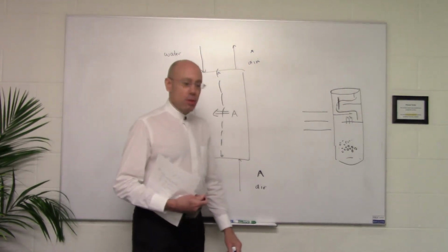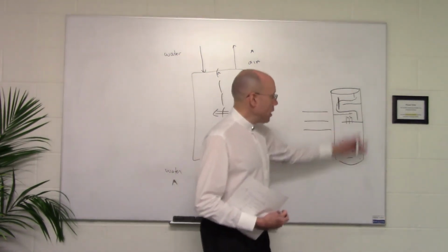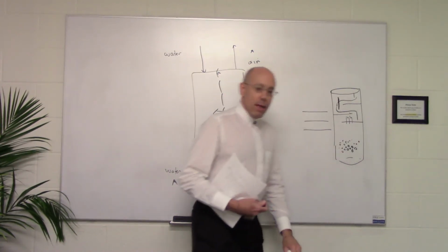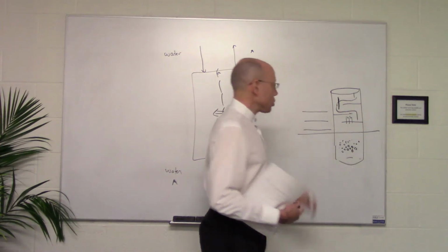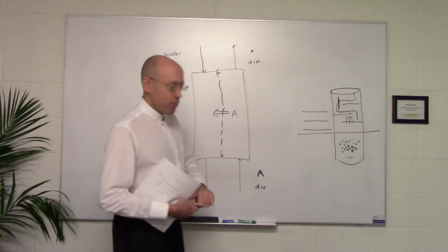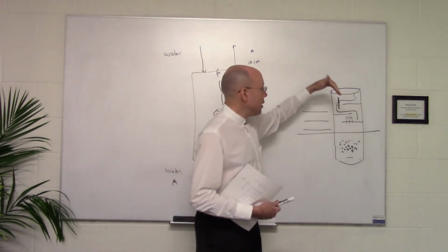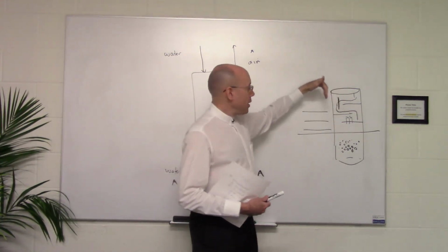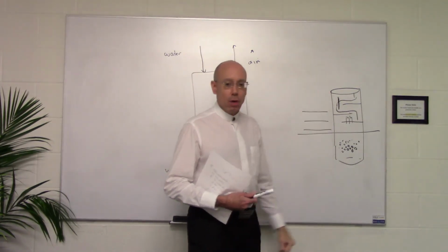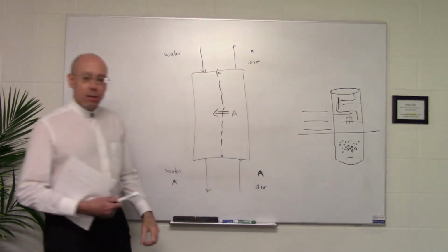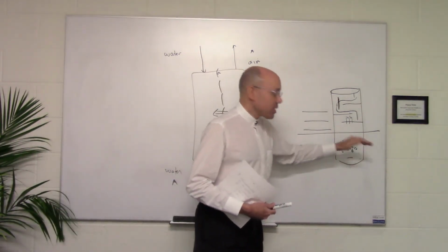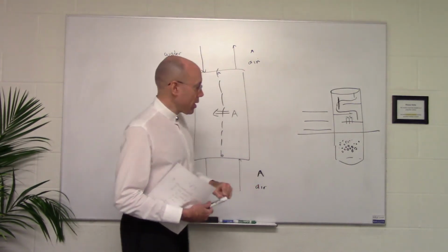And the contact between the liquid going down the tower and the vapor going up the tower happens in this random packing. So those are two inherently different approaches. And so some of the processes we'll be talking about, especially in the first half of the course, are stage-wise contact, which happens on individual stages or trays or plates, they can be called. And that's just inherently different from what happens in packed towers, where they have dumped in them a random packing.